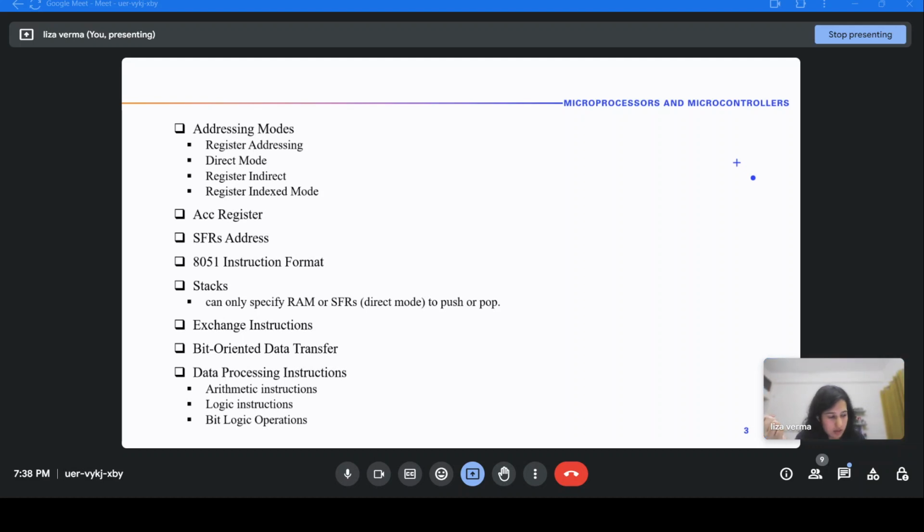Yeah, ma'am. I was also confused, but I have read these slides now and cleared my confusion. Last time I didn't pay attention while making notes. That time in 8085 it was incremented by two, but here by one. That was the confusion also. So by two and by one can be understood easily now, right? Since their stack pointer was 16-bit, here the stack pointer is only 8-bit.